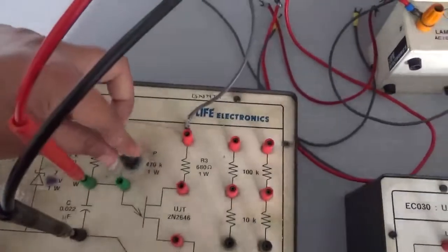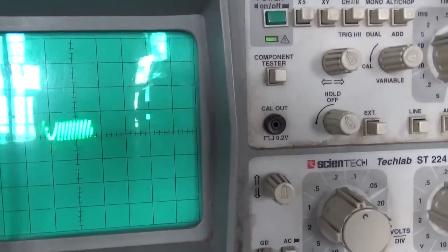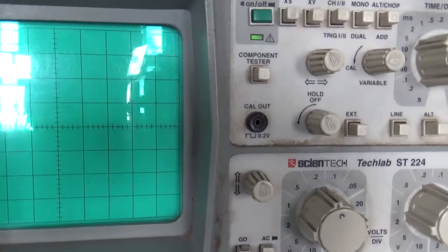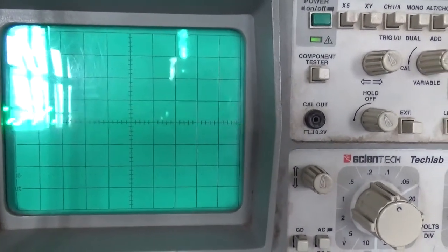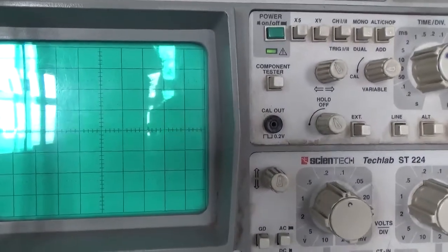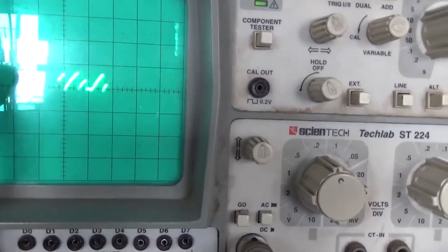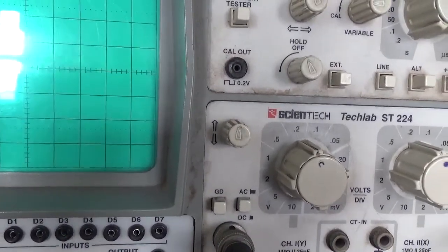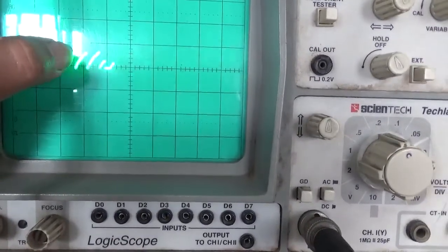See, now here I am varying this resistance. When I vary this resistance, this plot is going to change. The number of charging and discharging cycles per 180 degrees will change. While drawing in your graph sheet, it's not compulsory that you draw only 5 or 6 cycles. You can draw as many as possible. And one thing you need to take care of is that while drawing the next waveform, it should be synchronized.